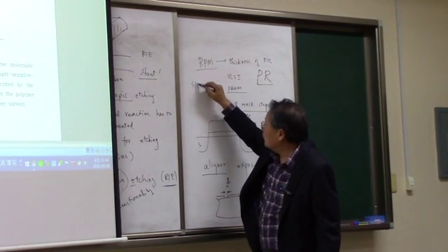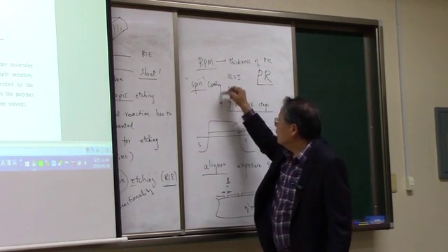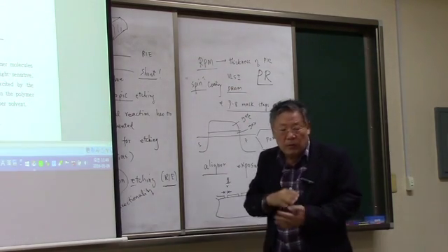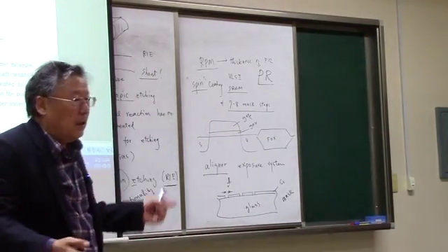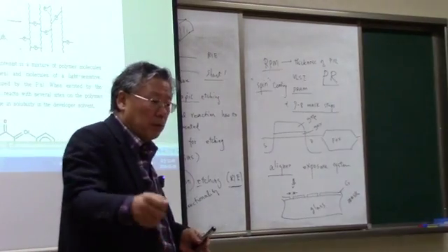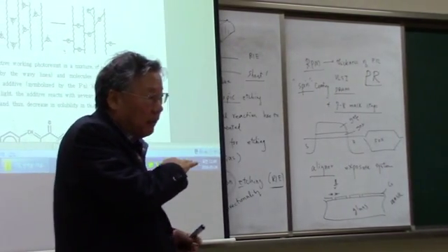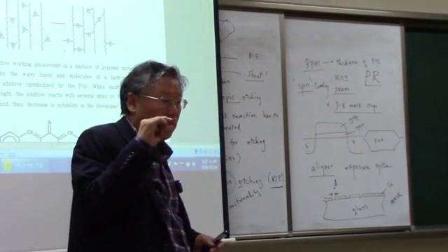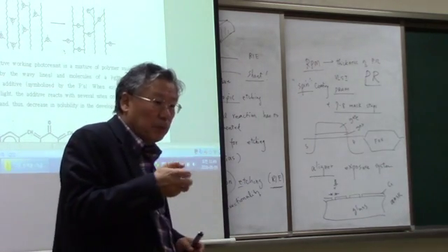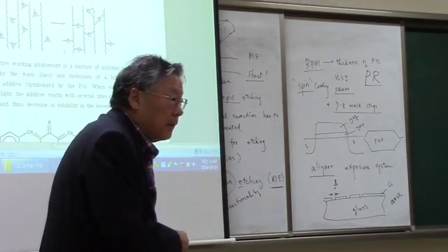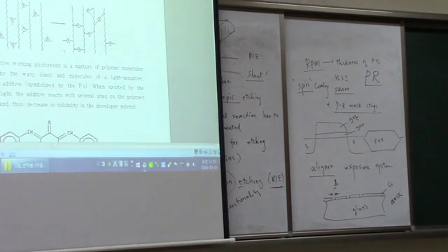Okay, so we call this a spin coating. That's how you form a thin layer of photoresist on your substrate. Long time ago, people tried to use a brush, but with the brush, you cannot have a uniform thickness of the photoresist. Okay? Before that, people tried to use a spray. So these days we just use spin coating.